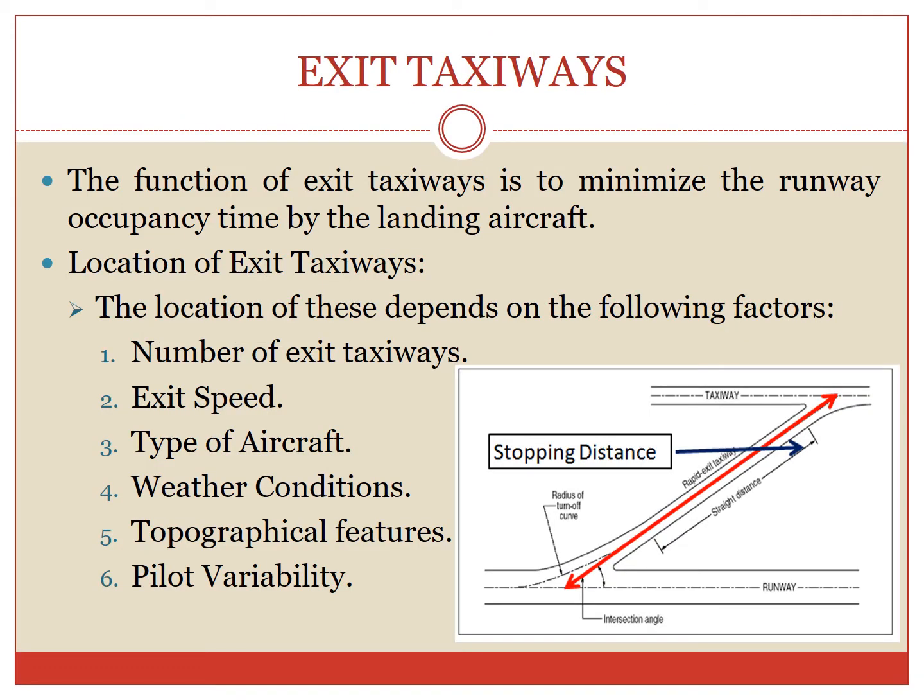Now next moving across to the exit taxiways. Now what are exit taxiways? The function of an exit taxiway is to minimize the runway occupancy time of the landing aircraft. The location of the exit taxiways depends on the following factors. The location of a taxiway is determined by the deceleration rate of the aircraft after crossing the threshold.